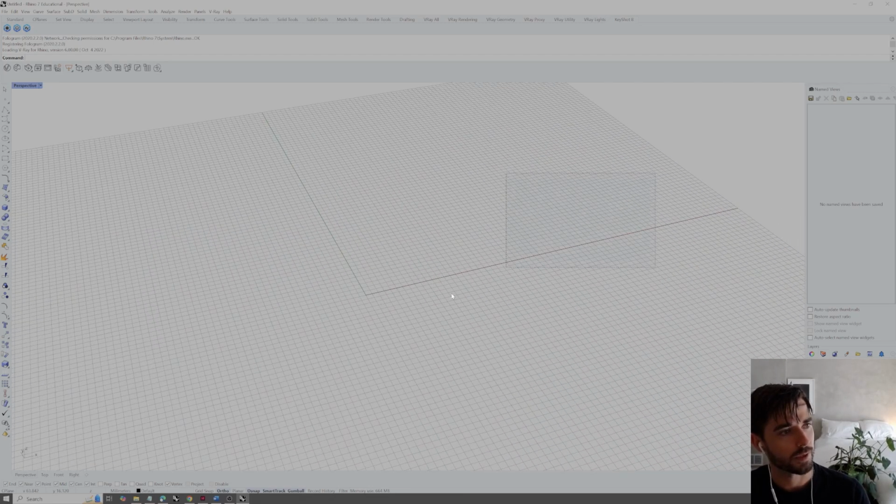If you don't want this grid visible, then you can just type in this command prompt up at the top. So this is our primary interface with Rhino. It is a command-based interface, meaning on this command line, we can just type whatever the command is that we want. So in this case, we can type grid and then hit enter to send it to Rhino to run. It gives us additional options for that command.